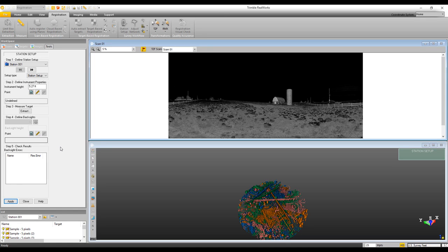So I'll do my full 360 scan, which you see here kind of in the top part of the screen. And once that scan's complete, I can isolate a specific area and scan it at a different resolution. So overall, this was just a quick 3-minute scan that I did out there, medium density. But there were some targets that were a little bit farther away, maybe 150 feet. So I did a higher density area scan on those targets.